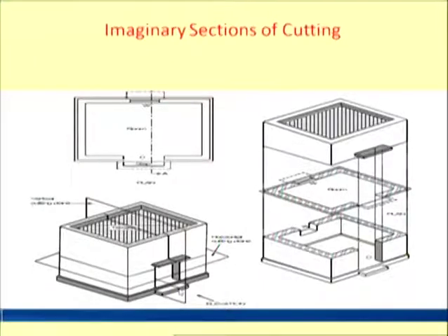Every step's vertical face is called the rise, and the horizontal surface of the step is known as the tread. So with 2 rises, naturally the tread will be 1. The number of treads is always the number of risers minus 1.